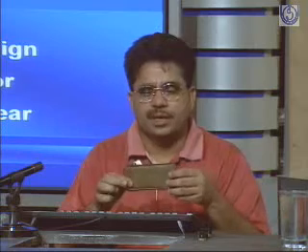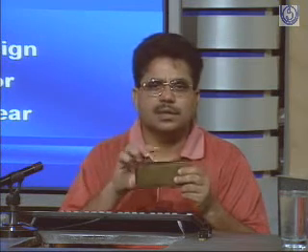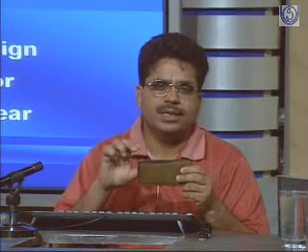If this is the beam and only pure bending moment is coming on it, the bending moment diagram will be uniform, and in that case no transverse shear force or shear stresses will come in the member. But generally this is not the case.